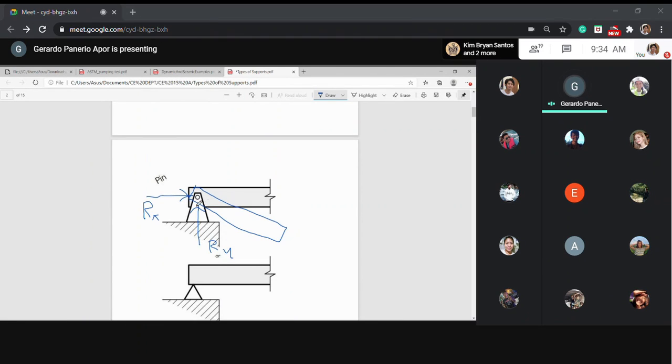the surface here, no? Sometimes when we analyze using long hand calculation, we convert a 3D structure into a 2D structure, but very seldom in reality can you find a 2D structure, unless maybe doors, windows, arcs. So they are 2D structures, but it's very rare. In reality, all structures are 3D.